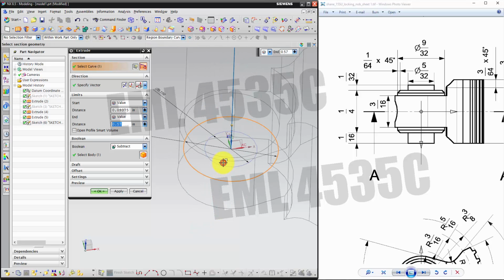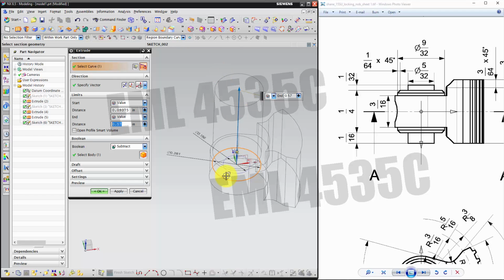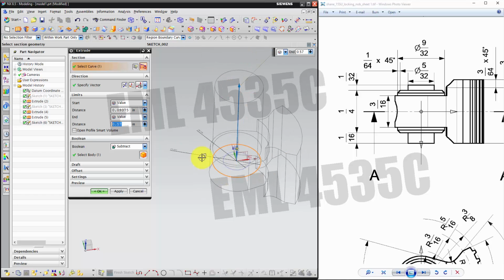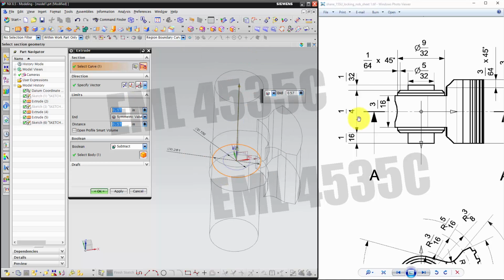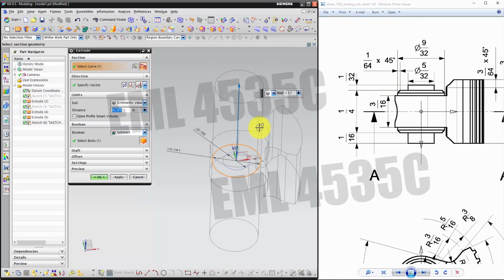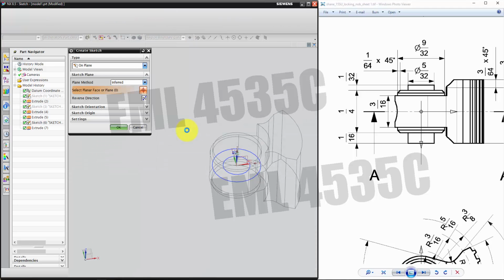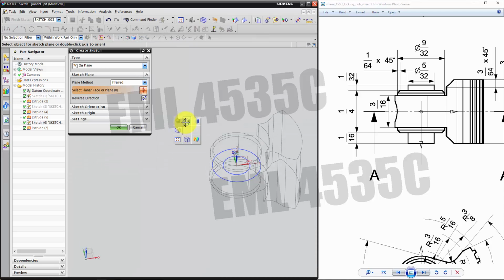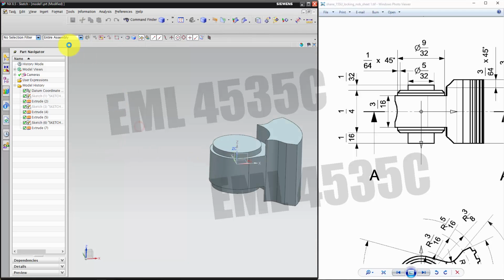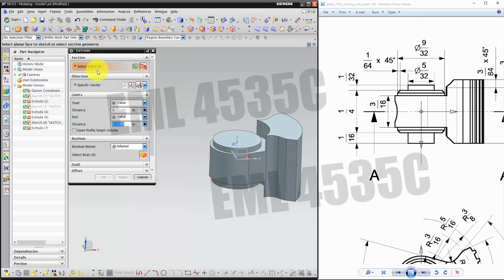So if you want to extrude the bigger cylinder, you have to select both regions. And it's a symmetric total distance, 1/4 inch, so that'll be 1/8. And be careful here, the Boolean is still on subtract. I'll turn this back to smart, invert and apply. Then you can take a look. Okay, then we'll do the second one.